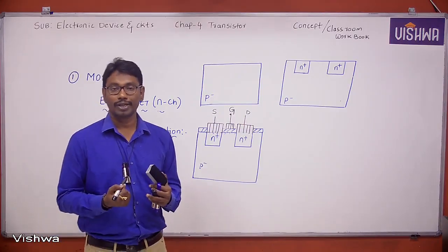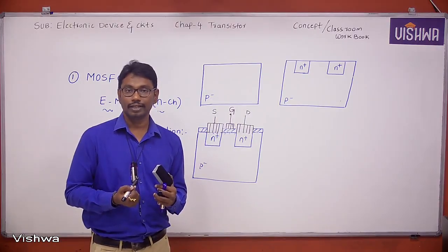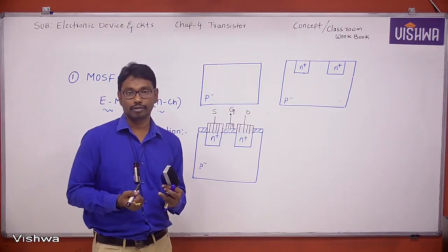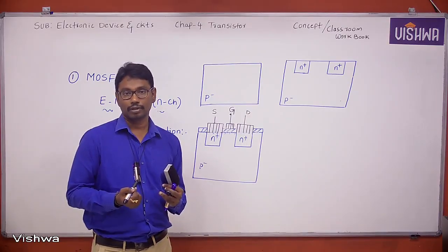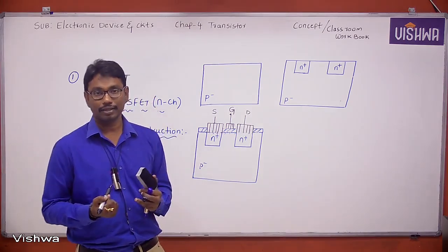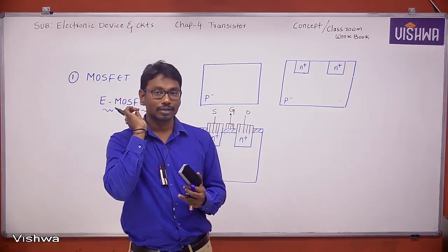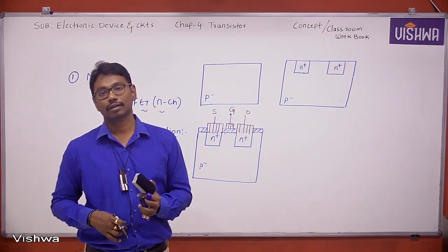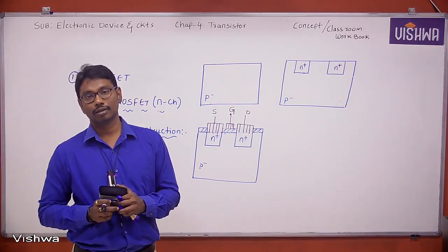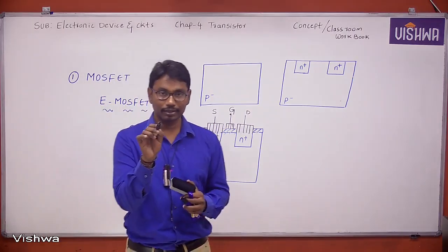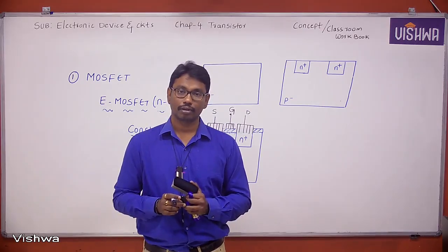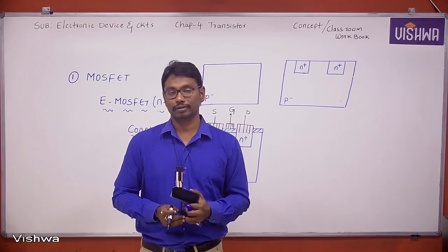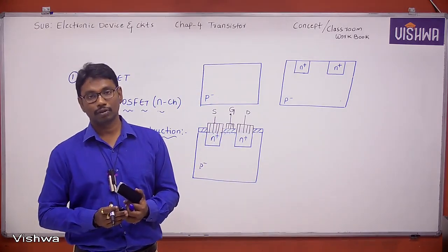An oxide layer is formed over the substrate by using the oxidation process. This oxide layer can act as an insulator, or dielectric, or masking. Underline: insulator, dielectric or masking. Next point: masking is the selective portion of doping.